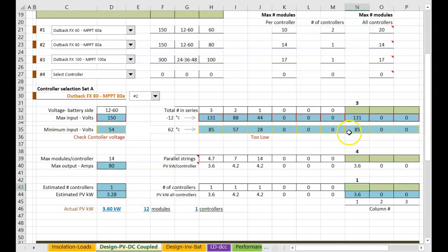It's a little bit low. And if you needed more than 1 charge controller, you could do 2. Say, hey, let's beef it on up. Now we have a 7.2 kW PV array. Or you can go over here in these inputs and say, let's do 3 and 2 and 1. So we have 1 charge controller that's putting out 1.8. I'm going to go back and put 1 in here, and 3.6. So now we have a 5.4 kW PV array.